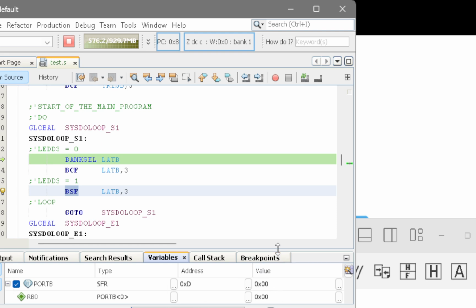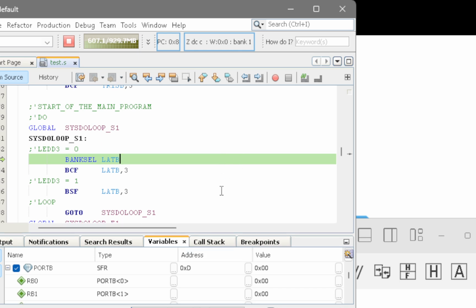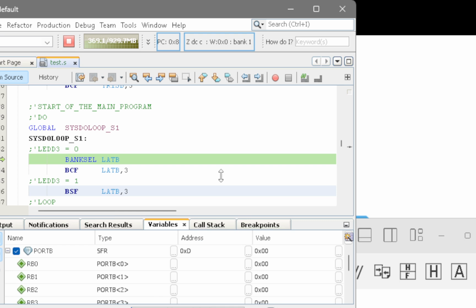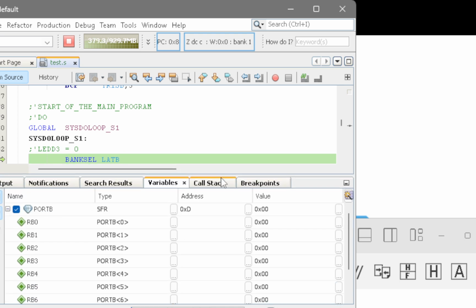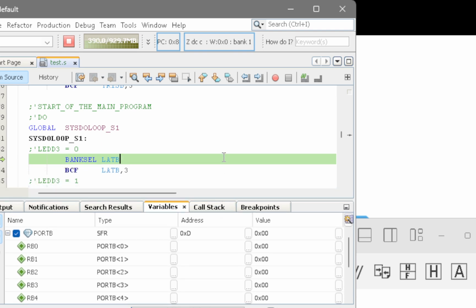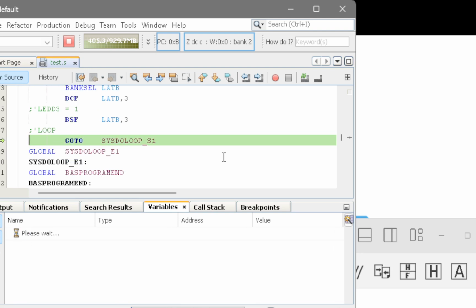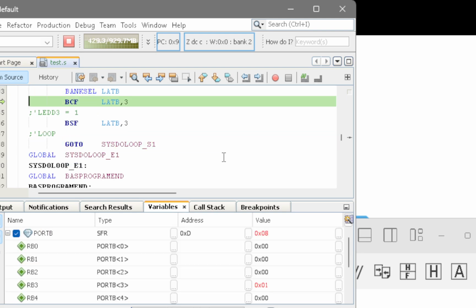I'm going to pull that up a little bit, just so we can see enough of this, okay? We don't need to see all of it. We need to see bit 3 though, don't we? Because that's the one we're playing with. Come on, get up there, boy. That's a bit too far. Here we go. Function key F7 to walk in the compiler, in the debugger. Bit clear, bit set. Bit clear, bit set.